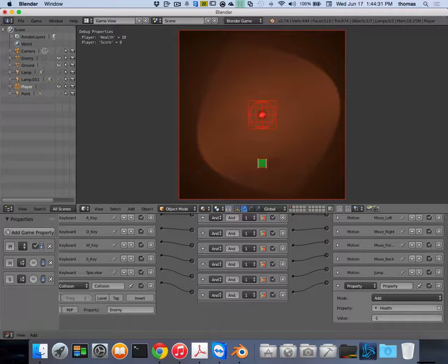My sphere, my bounding box for my sphere is huge, right? For some reason. Probably because I changed the units and messed around with that. And that's why whenever I play, if I go in here, look what it's colliding with. If I want to debug, I can see where my bounding box is, because my bounding box is what I'm colliding with. And I can turn physics visualization on and off. It's a very important thing. I just went right through it, look.